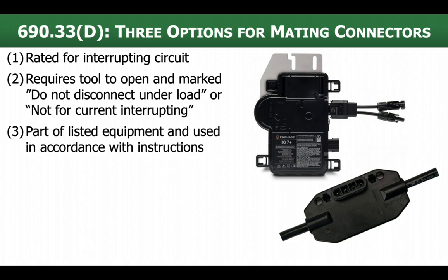Maybe, maybe not. It depends on the particular device, as I said. But don't be surprised to see that. It happens all the time. They say you can't, but the instructions say otherwise, because it's part of the listed product that came, that wiring harness there that plugs into the micro and into the module. That's a listed device. And so if we're following the instructions and it says you can, then hey, I can use that as a DC disconnect. The same would be true maybe on the AC output, the trunk cable. May be able to open it under load, maybe not. It all depends. We're going to look to the instructions for clarity on that.